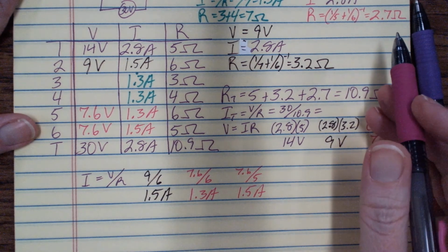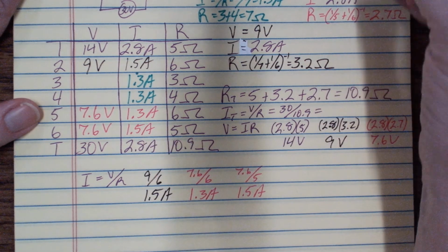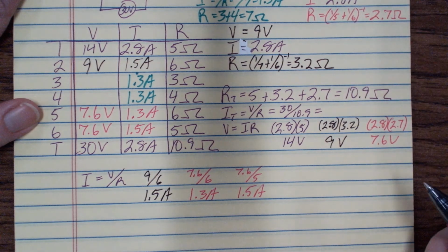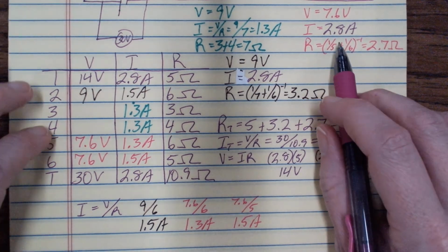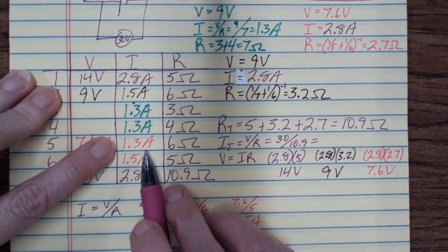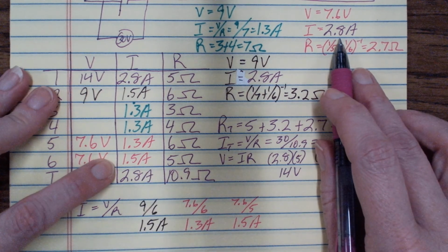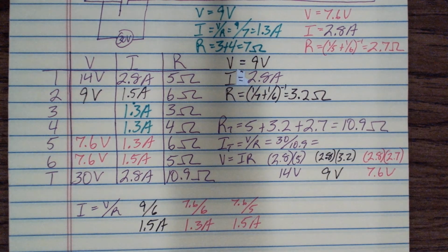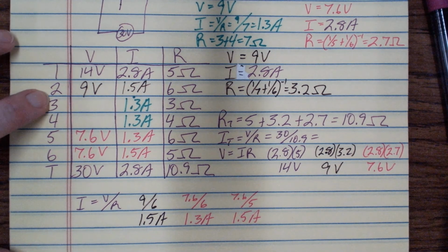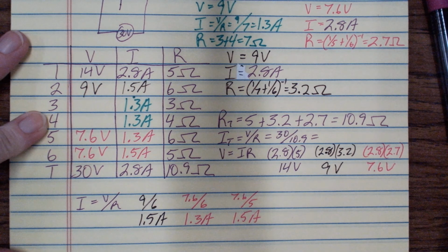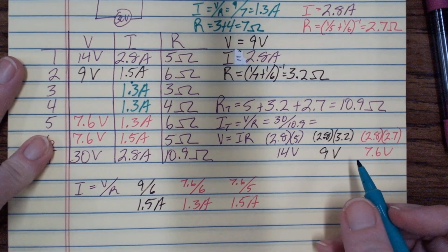And I can kind of double check that. Actually, I can kind of stop for a second and say, okay, so if I add up the current on resistor 5 and 6, I should get the overall current on the pink box, right? So 1.3 plus 1.5 is 2.8. The current on the pink box was 2.8. So I'm still doing good with my math, okay? And so then I just have one last thing to do, and that's to find the voltage on 3 and 4, okay? And they're inside the green box. I'm going to switch back to green.